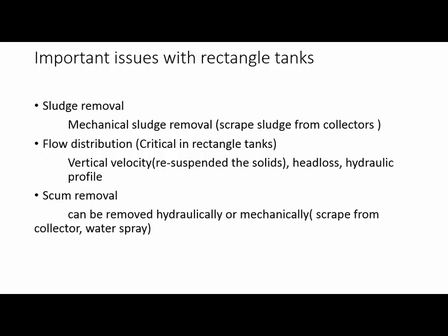Flow distribution is the critical part in rectangular tanks, and there are some important parts of the flow distribution. You must be careful about the vertical velocity, or if you don't pay attention to that one, it will resuspend the solids in the bottom. And another is the inlet and the hydraulic profile.